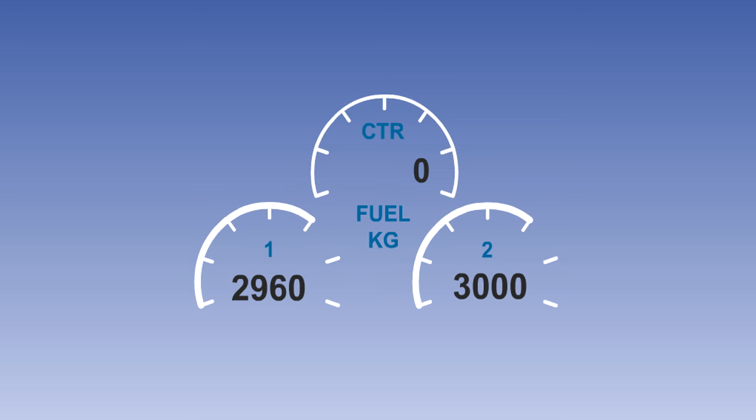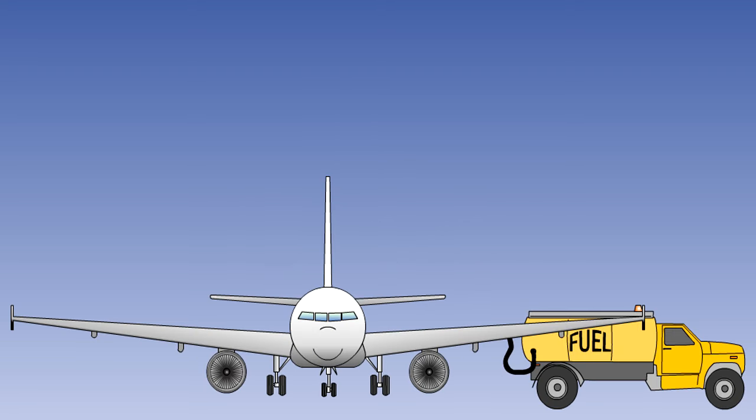On modern aircraft fuel systems, this usually makes little difference, as fuel in the aircraft tanks is measured in mass or weight rather than volume, with the fuel quantity measuring system compensating for changes in fuel-specific gravity. However, if a high fuel load is required, it may not be possible to get sufficient volume of fuel on board for the required mass if the specific gravity of the fuel is low.